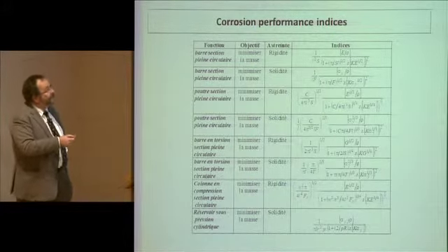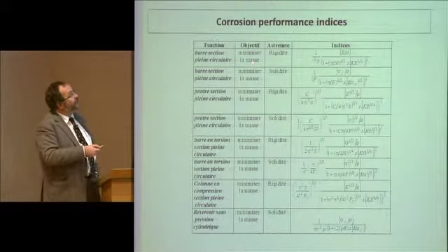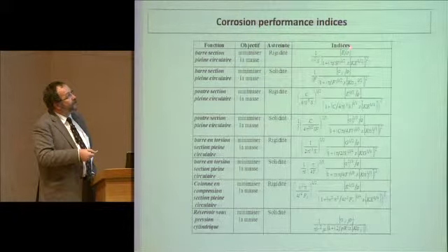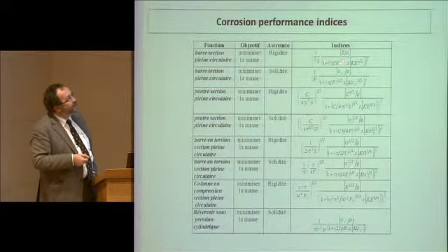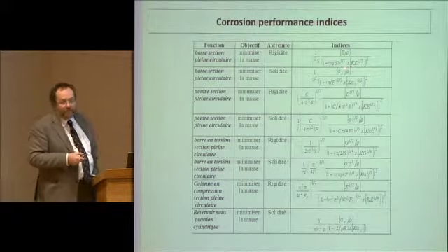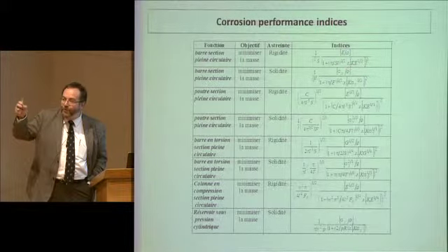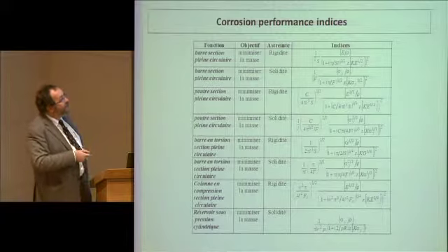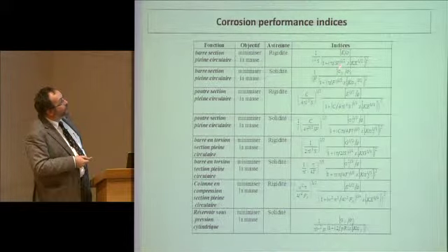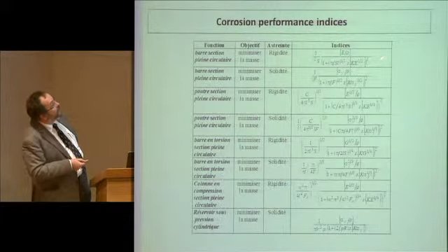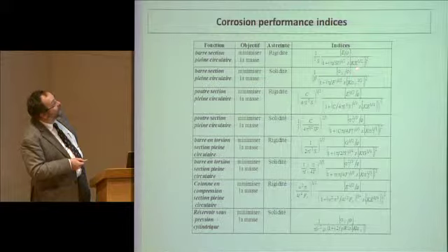So this is exactly what this index says. The performance index for this particular situation is the modulus divided by density, divided by this horrible little formula here, where you have a constant which is the material erosion constant in an aggressive environment, and you can see here the time that's factored in, the time for which the part needs to operate.